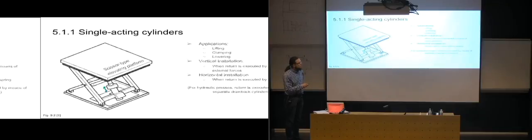And for hydraulic presses, where you're using them in production, where you're actually pressing something together, for an example in a casting, where you're pressing two molds together when you are casting something. The molds themselves are usually so large and heavy and require quite a lot of force, so the cylinders push the molds together, but then you have separate cylinders that will push them back again.